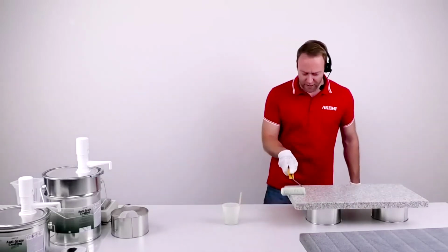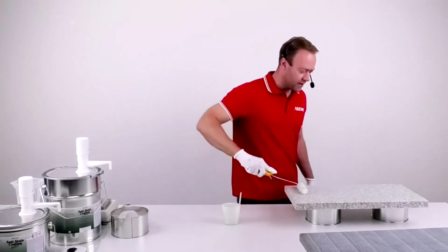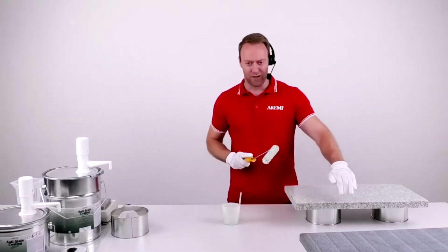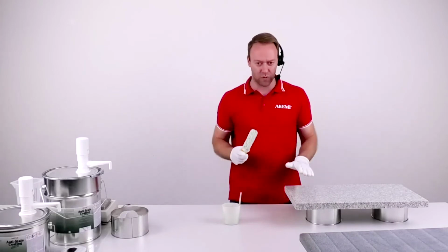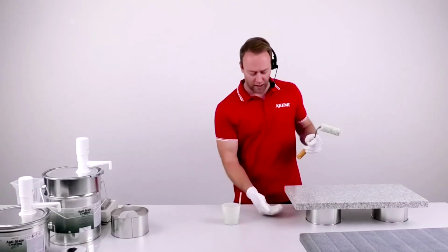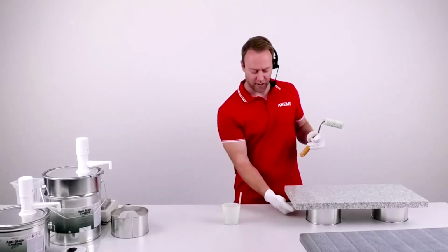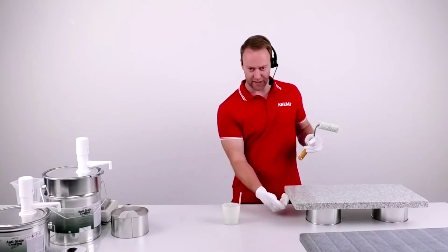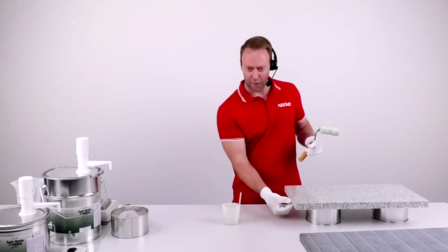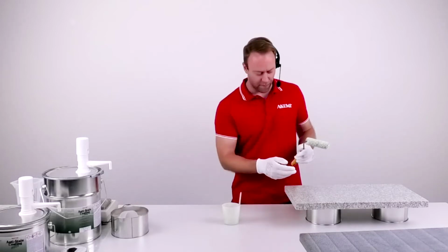Now comes the important part, the lateral sides. As we said, we need to cover a little bit of the sides, because what does the humidity do when it comes underneath? It tries to pressure through the stone. It cannot. It tries to evaporate over the joints, and then it goes up here. So we have to cover at least half of the side with the anti-stain.